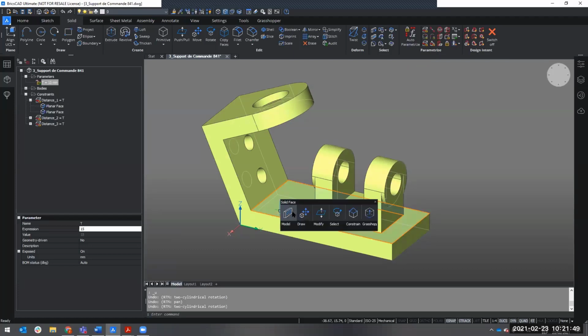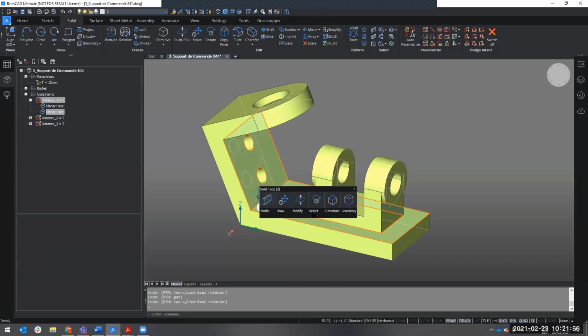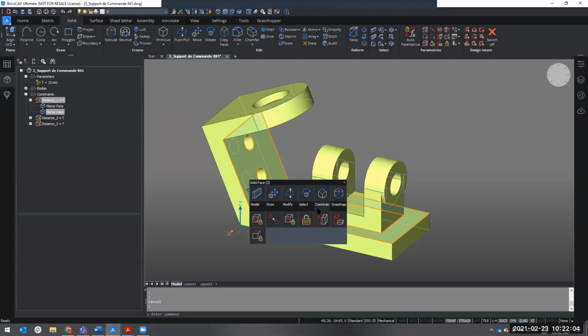You can also select a face and then two faces, I believe, and press the constraint tab. So if you click one face and hover over the next face, you can use the quad and it will tell you which constraints can possibly fit this type of selection, namely two faces. And you have here the add angle, the same icon as well.